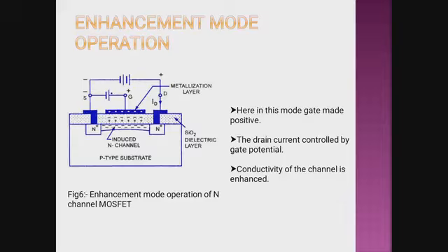The main difference between DMOS and EMOS, DMOS meaning the depletion MOS and EMOS meaning the enhancement MOS, is that from the diagram we can see the substrate extends all the way to the silicon dioxide and no channels are doped between the source and drain.